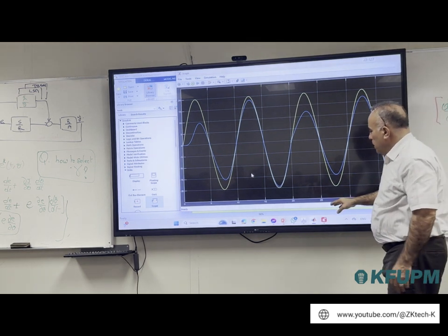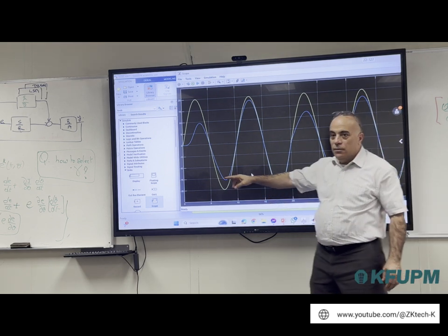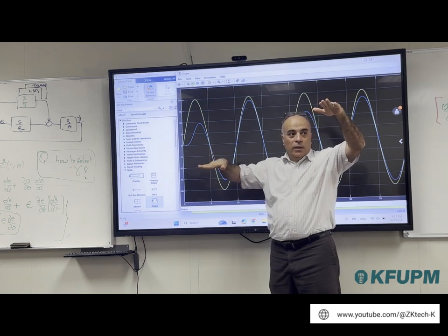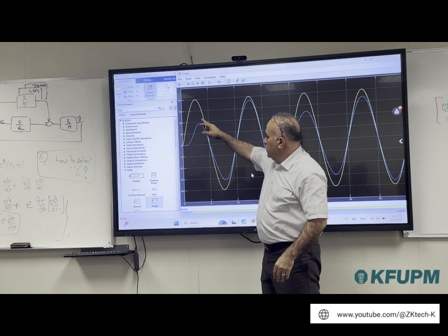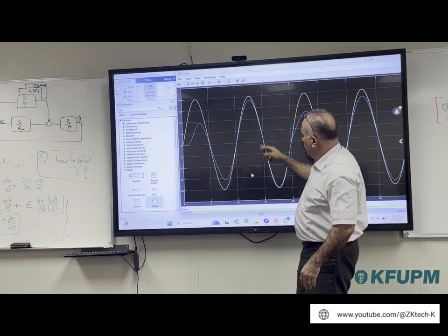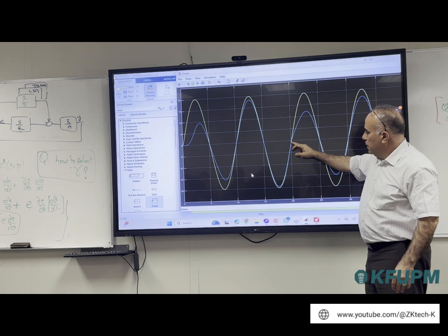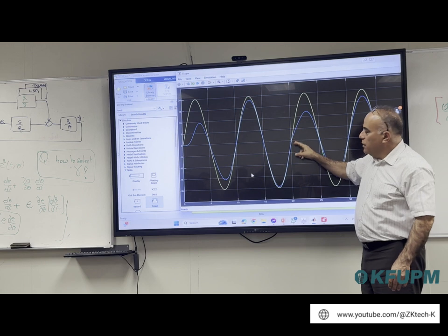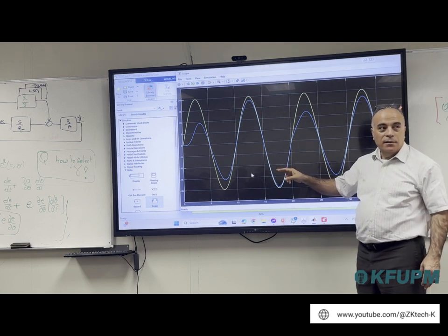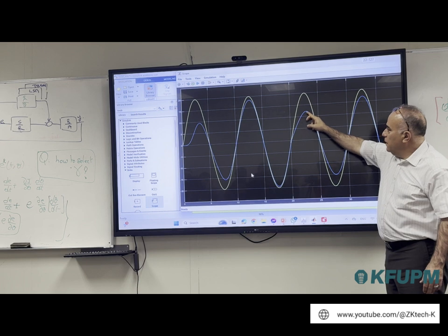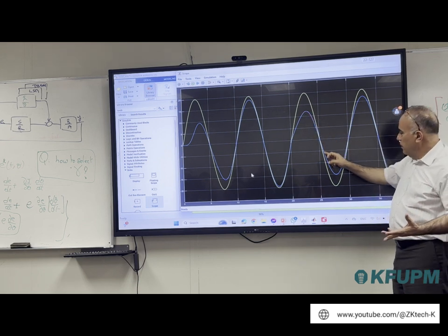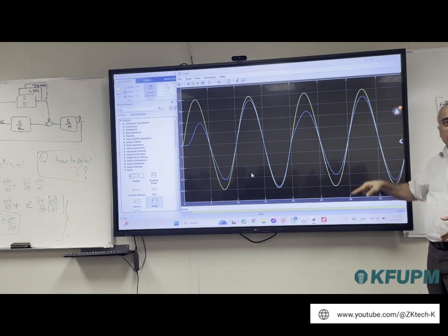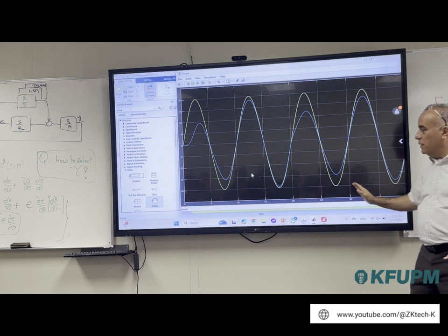Alright, see here what I did is that the system is trying to adapt. So I start with different gains, one equal to 10, the other one equal to 1. And then the system starts correcting. You see here, there is a correction action coming. Up to this point, in this correction action, it has almost the error equal to 0. Then I change the controller gain. And then you see now it's different because they have different gains, and the system is trying to recover again and identify again. If I come here and change the gain, it will do exactly the same thing. And this is every 20 seconds.